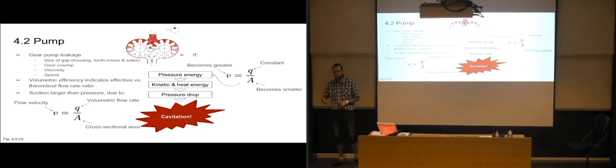So if you are creating a hydraulic system and you have a pump that's designed to be run at a range of 1,000 to 1,500 RPMs, it really won't be good to connect it to a motor that's running at 2,000 RPMs, because then you will have too much velocity in it and you will get cavitation inside.